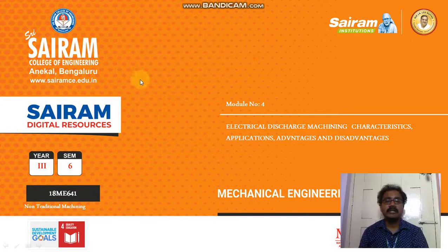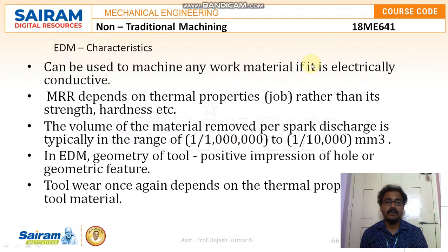Hello everyone. In this video, we will be discussing electrical discharge machining process characteristics, its applications, advantages and disadvantages. So first, when we look at the characteristics of electrical discharge machining, it can be used to machine any work material if it is electrically conductive.